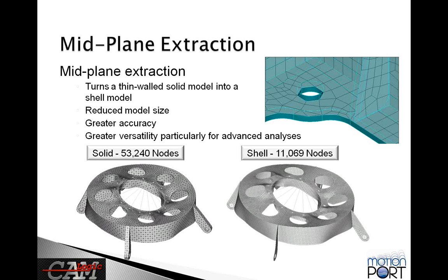There's nothing defined there by the CAD system, but Femap can take that solid geometry and automatically create that midplane so that you can do that fast conversion to the shell elements and then help you connect up the midplanes with other midplanes. And as you see in this model where we have a thin-walled part that's undergoing certain loads, the proper representation of shell elements can be handled very well.